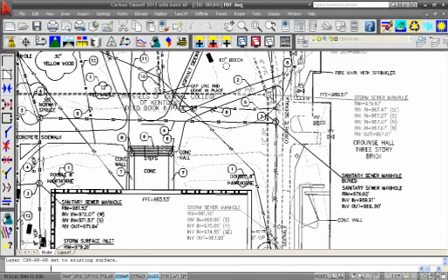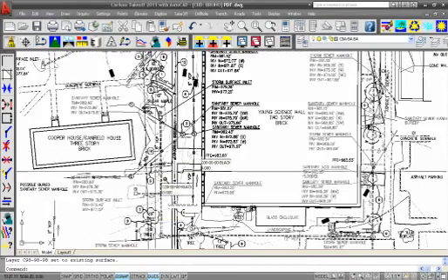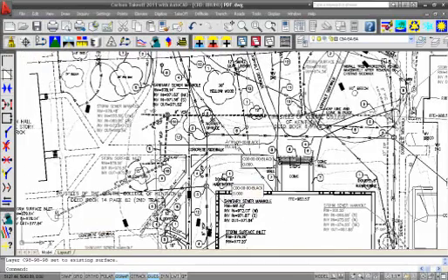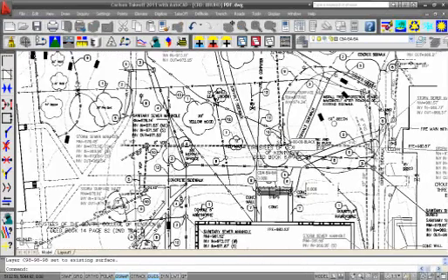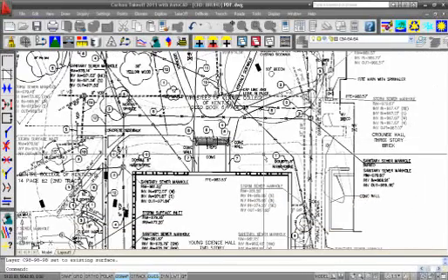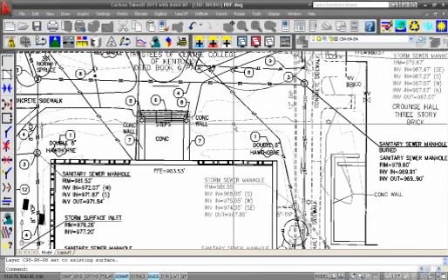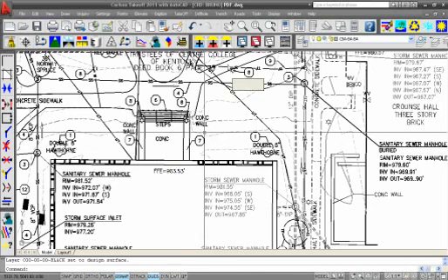existing. Now, how did you know that was the existing? Was that through drawing inspector? Yeah, just looking at the drawing, these contour lines look like existing contours. They're not going through the building, and it's just kind of a judgment call that I'm calling these existing contours. Because obviously from that file we need to find out what the existing is and what the proposed is so we can get the differences. Right. So it's important we find which layers, which line work is attributed to which file format, whether it's existing or proposed. Right. Okay. Yep.